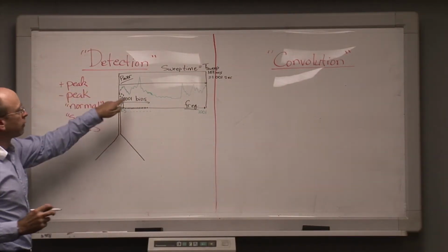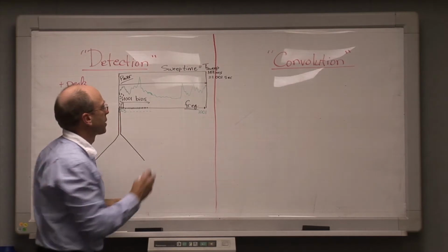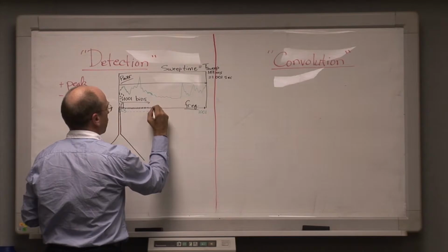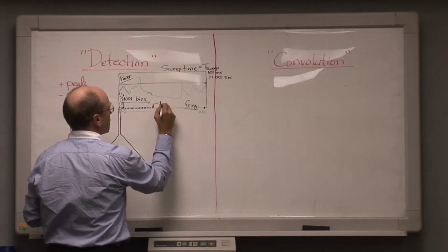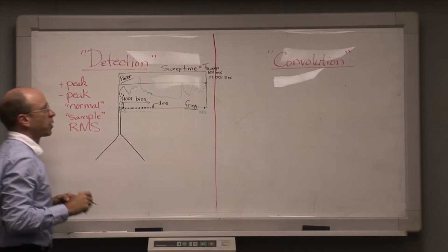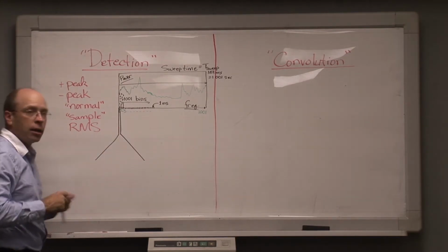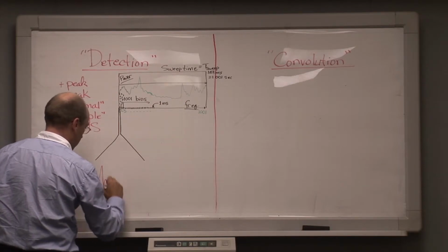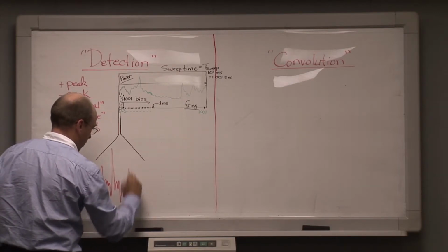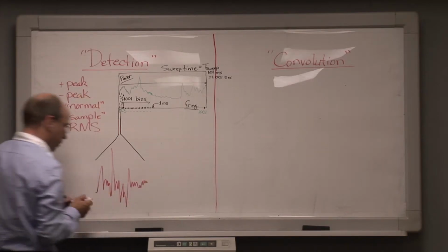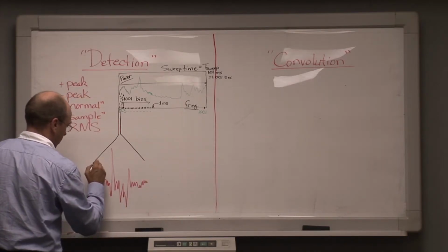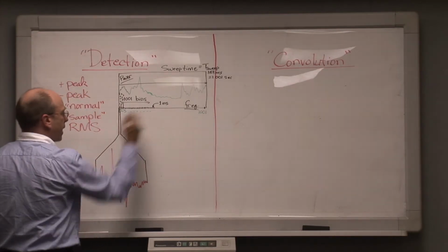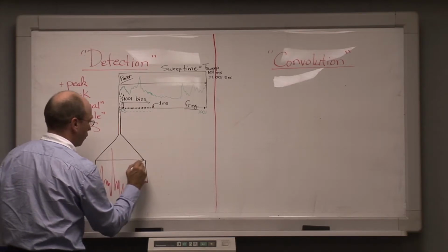That means that if we're doing 1001 bins in 1001 milliseconds, this spectrum analyzer is taking a total of 1 millisecond of sweep time for every bin that it's displaying. But the waveform that we're trying to measure, which might well look like this in the time domain, characteristic maybe of some type of noise, will in fact vary within that interval. So here we have an interval of 1 millisecond.